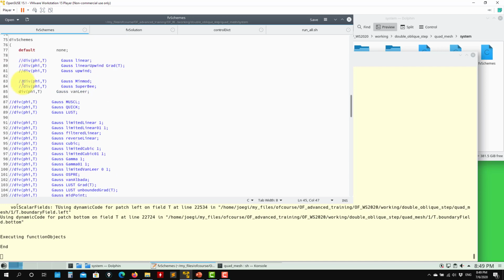Then when it comes to the divergence, the convective part, my advice always, this is very accurate. Okay, always stick with this one. And the linear upwind, second order upwind. But have in mind that you can have the upwind, a good TVD, and a linear, then in this case it's a little bit unstable.